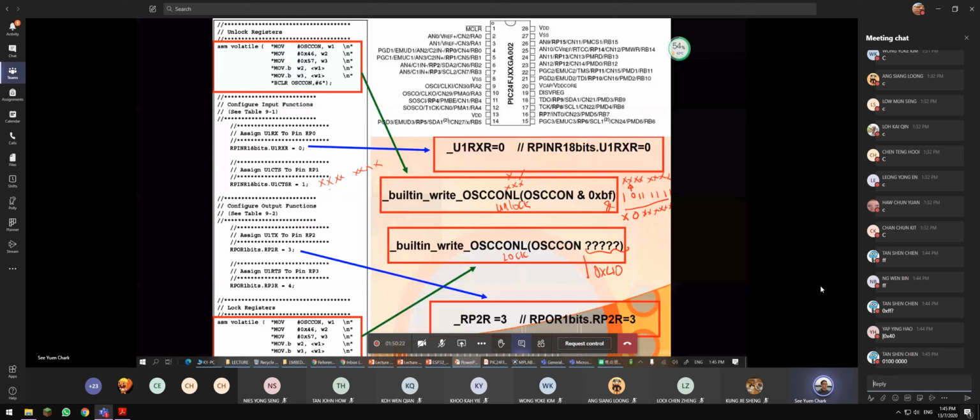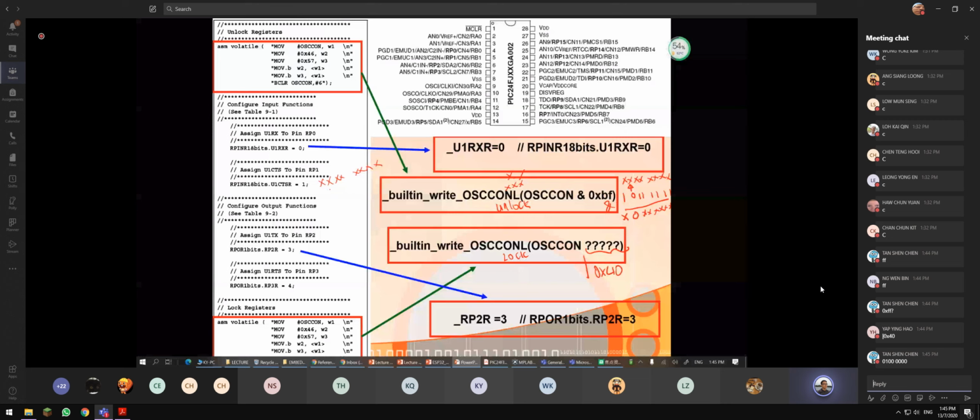If I OR with 0x40, that is 0 1 0 0 0 0 0 0, OR-ing with the rest, if OR, don't care. No matter if it is 1, don't care. So it's quite straightforward, am I right? Sheng Chen, very good, it's an OR gate. Good try for Wing Bin.